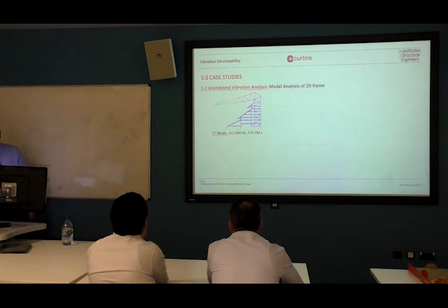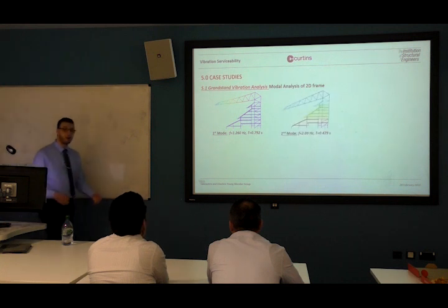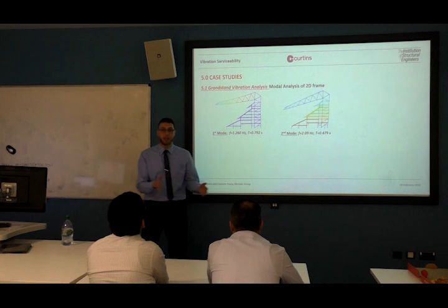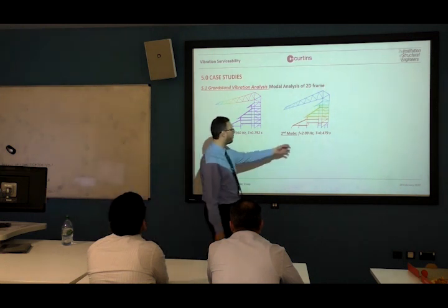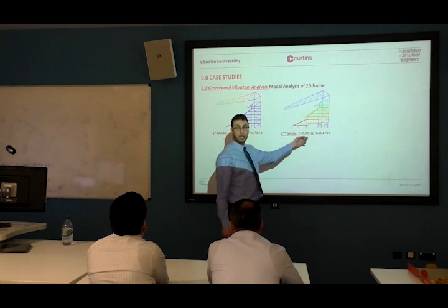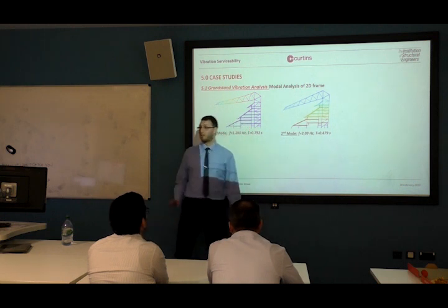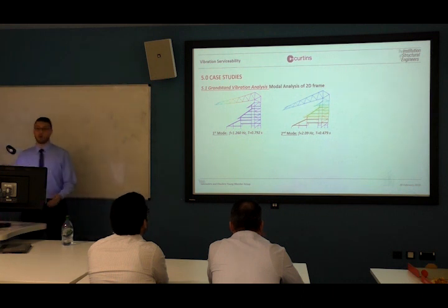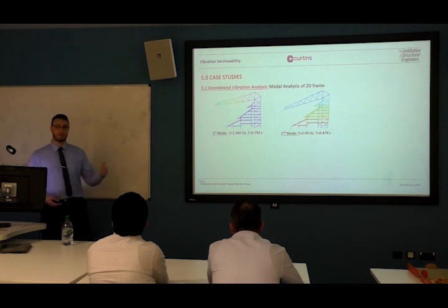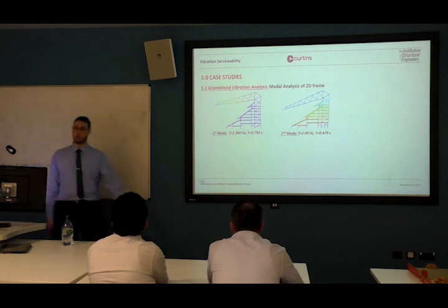Okay, move to the second mode. The second mode is the whole stand swaying. How much frequency do we have? 2.1. It's greater than 1.5. That's fine. We don't have to check this one either, because the sway motion of the crowd will not create resonance if the frequency is higher than 1.5.